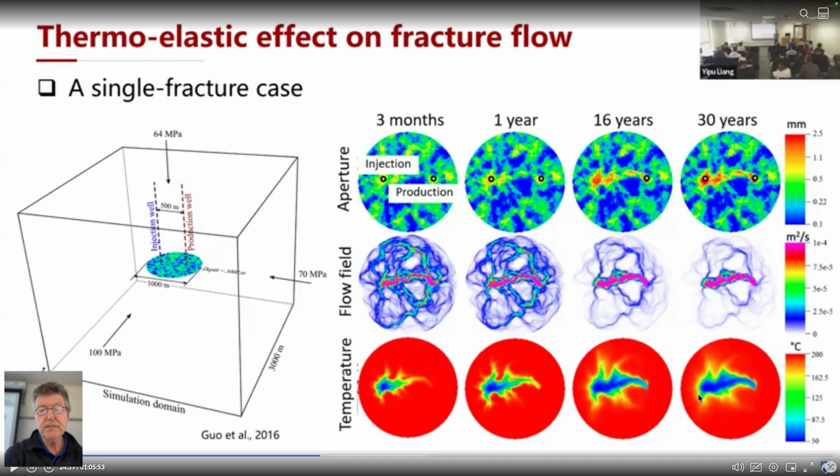And if it expands directly between the inlet and the outlet, then that is cold thermal breakthrough, and you might have a large volumetric flow rate, but you might be producing at no delta T. So you inject at 30 degrees centigrade and you recover at 30 degrees centigrade.